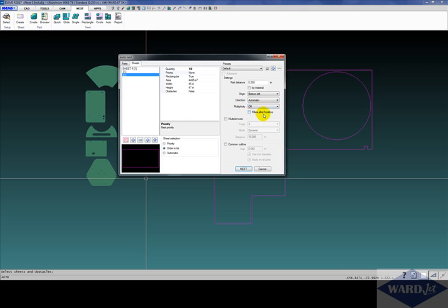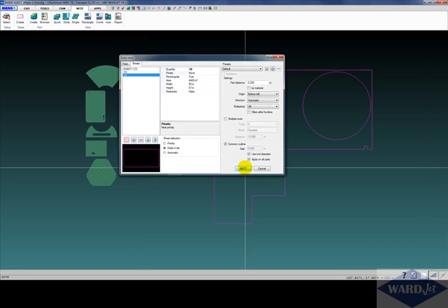Then you've got the choice for fillers after frontline. So if this box is unchecked, it's just going to use the fill parts up to wherever it finishes on the sheet with the required quantity of parts. If you check this box, then it'll end up using the entire sheet for the balance of the entire sheet for the fill parts. And then you've got your choice for whether you want to use multiple cutting heads, and then whether you want to use common line cutting. So we'll go ahead and check that, and then click on Nest.